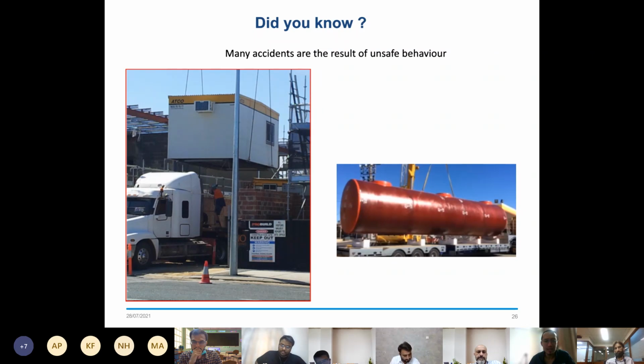So that's why, mostly in my experience, I just want to share what we did in my last experience. Of course, the crane is always there whenever we need to lift any equipment like containers or tanks. So what do I do? The rigger wears the safety belt, and we go up the ladder. He goes up to the top of the tank or container. We hook the lanyard to the crane, and meanwhile he hooks up all the tackles. Then when he comes down from the ladder, we remove the safety harness. So usually we do this practice.